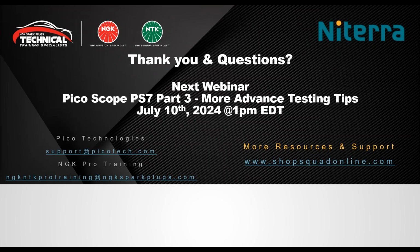Correct. So if I'm worried about cam and crank, first off, I'm going to be testing it at the PCM or whatever the controlling module is. I won't be testing it outside the engine compartment or in the engine compartment with my leads laying across everything, because I know it's going to create an issue. I want to see what the computer is going to see, and then I always start with unfiltered.